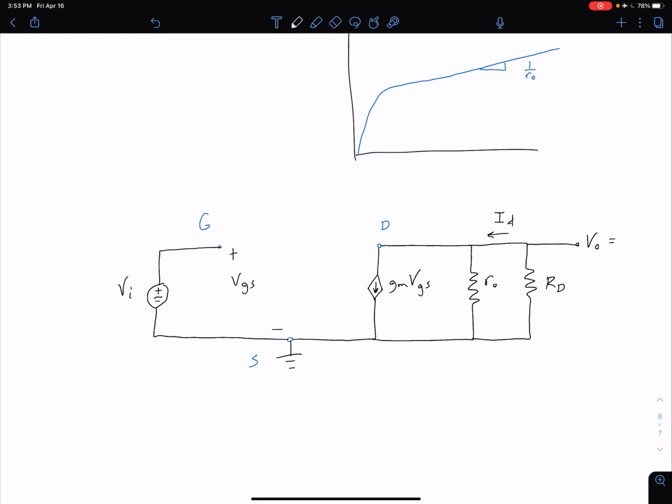And we can also note that that is the voltage between our drain and our source. So again, that's going to be phasor notation, uppercase V, lowercase ds. So again, just for clarity, all of this here, so not including that ground, is our actual transistor model. And then everything exterior to that highlighted circle is going to be the rest of our circuit. So that's going to change depending on the topology of our circuit. So this is our transistor model.